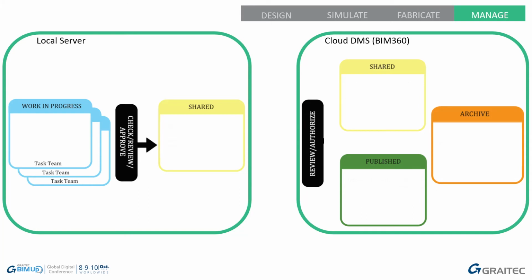Let's turn this into some documents to see what it's going to look like. So I've just created some names just here. We've got a model and a drawing. In your work in progress, the status will be S0. The revision will be whatever revision is going to go out next, with a sub-revision afterwards showing your internal status of what's going on with that file.